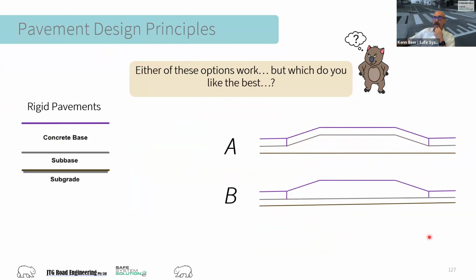What's the minimum ramp length that can be compacted effectively? I'd say around about a 1.2 meter length ramp can still be compacted, and even less than that can be compacted. It just changes the machinery that's used. I like a standard 500 millimeters minimum for compaction areas because it's a good size for the larger hand compaction tools, hand vibrators.